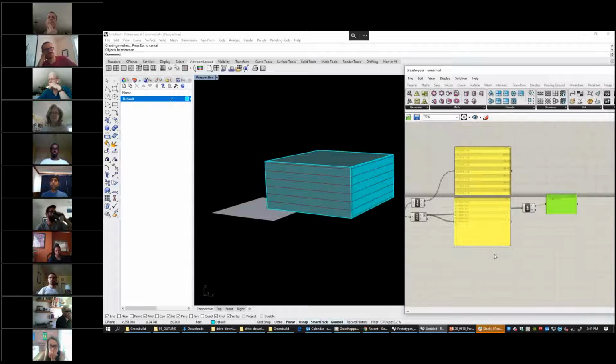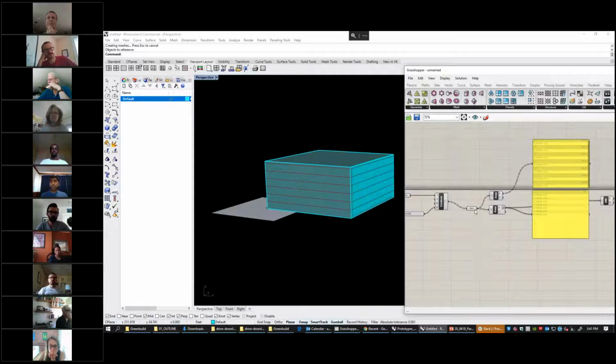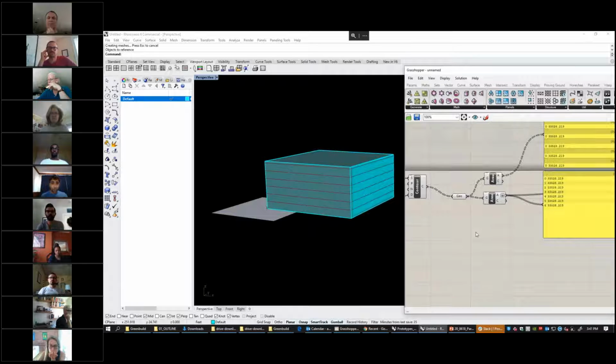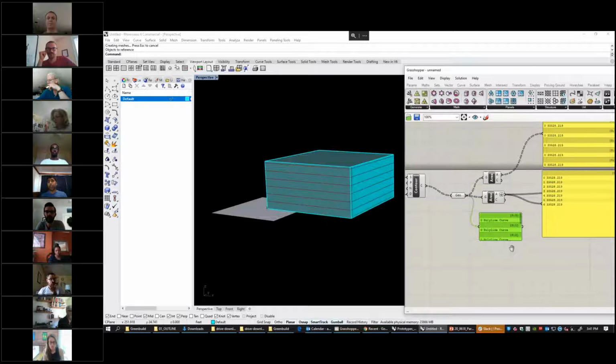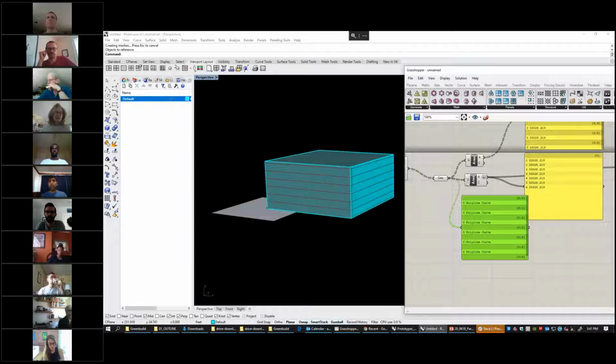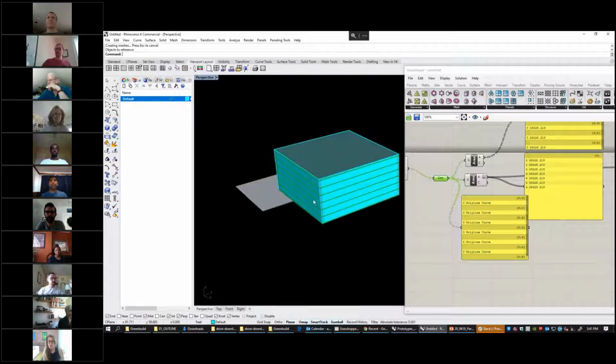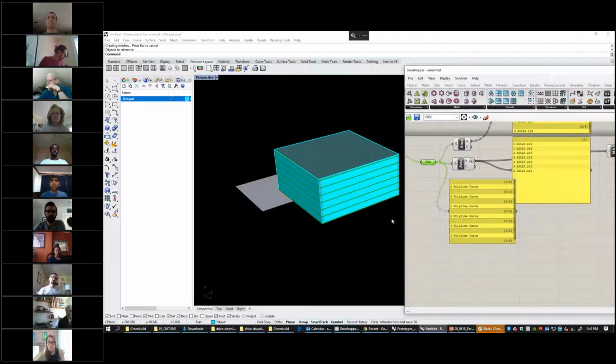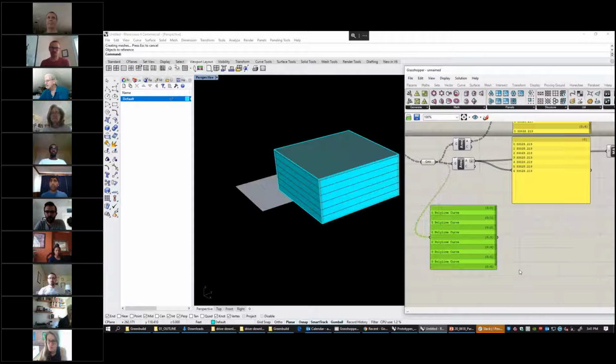But then let's look at the contours again. The contours are these, let's look at actual lines. It's these polyline curves. It's the rectangle, 4 lines in a circle. But if I want to get these individual lines and know, let's say, the length of this face versus that face, you need to take that polyline and explode it.